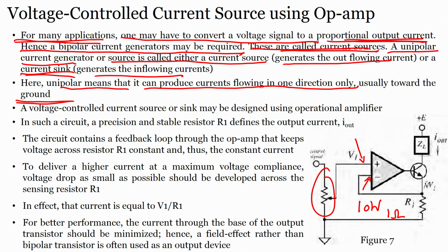So, when this happens, the transistor conducts, and the current across this resistor depends on the voltage we have applied over here, because it is trying to follow the same voltage. Depending on that, if you have your emitter current here, then the same current will be there in the collector.